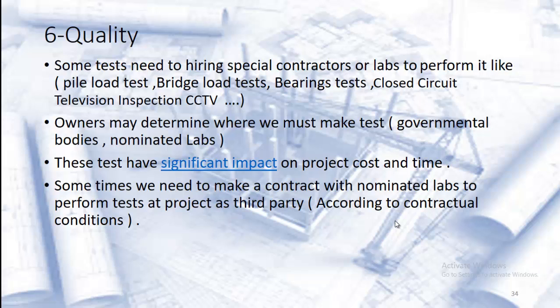Like if we take the pile loading test, we need to bring a contractor, or if we have this equipment we need big steel beams, sandbags or concrete blocks, and monitors, gauges, and others. All this needs to be prepared for this test. So we need to hire a special contractor or lab that has experience in this test.